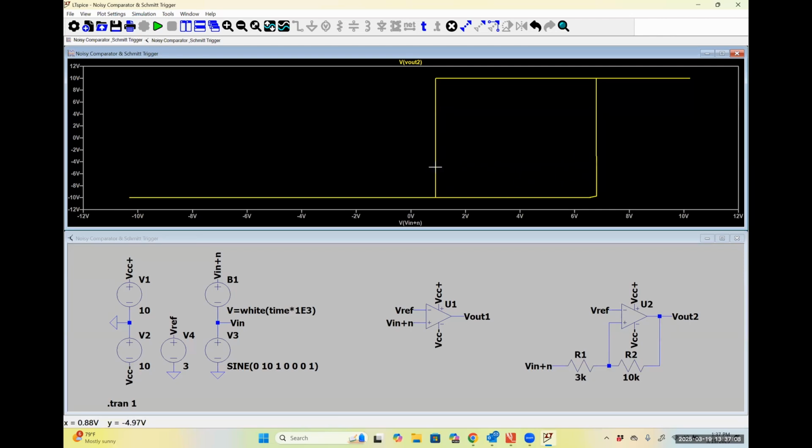And pretty similarly over here, for my lower trigger limit voltage, it has X equal to 0.89 volts, which is pretty darn close to 0.9. So this is doing a pretty darn good job of approximating what those upper and lower trigger limit voltages are, despite the fact that we've made some assumptions about how this thing behaves, okay?